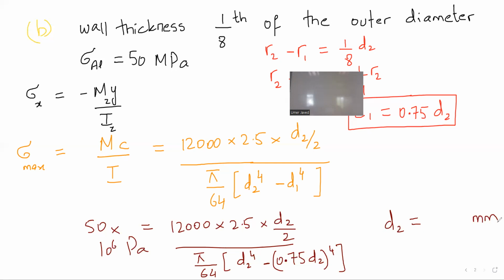I am using this because, first of all, it's pretty clear to me just by looking on which surface I will have tension and on which surface I will have compression. It's a circular object. On the chunk above the neutral axis, the whole semicircular chunk, there will be tensile, and below this line, I will have compression.